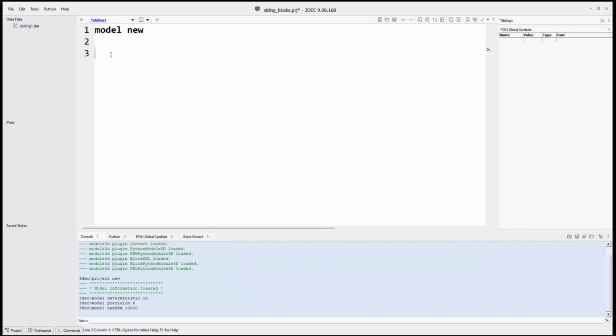There are other ways to import from other programs where maybe you've created a whole bunch of blocks in some other CAD program and you just want to import them and turn them into 3DEC blocks. This is certainly possible. For this example, we'll start with a big block and cut it into smaller pieces. So block, create. This is how you create a block. In this case, we just want to create essentially a 6-sided shape. The simplest thing we can basically create.